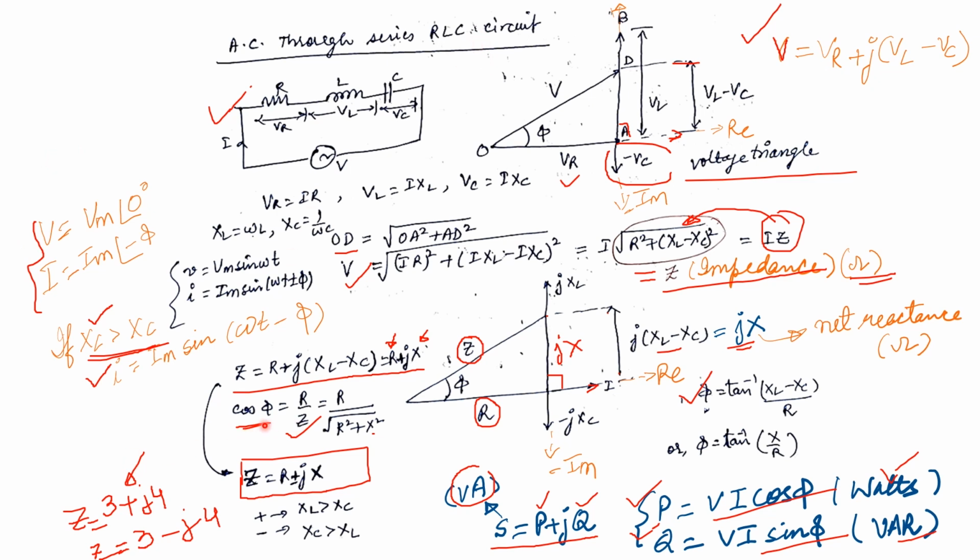if we are defining the power factor, we need to mention the word lagging or leading, or the unity power factor with that, right? So for this series RLC combination, we have assumed that XL is more than XC, so the nature of the circuit is inductive, and the expression for the current that we have written is I equal to Im at angle minus phi. This sign of the angle of current decides the nature of the power factor also.